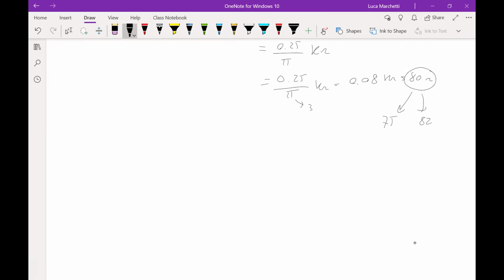Which do you think is the best? Well, the solution is 75 ohm, because if you use 75 ohm, the cutoff frequency is a little higher, and you avoid letting in more noise that you don't want. If you increase the resistance, the cutoff frequency becomes lower, which means you let more noise pass in your filter. So the best value here is 75. But it can also depend on your application. In this case, we can assume that we don't want the noise outside the filter, so 75 is the best solution.